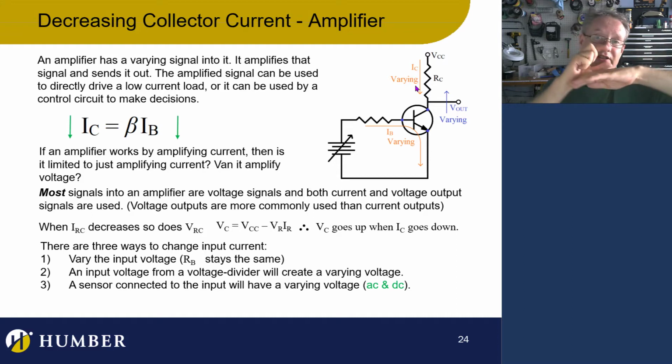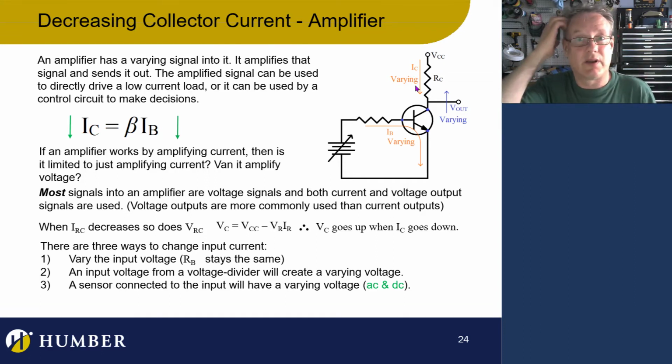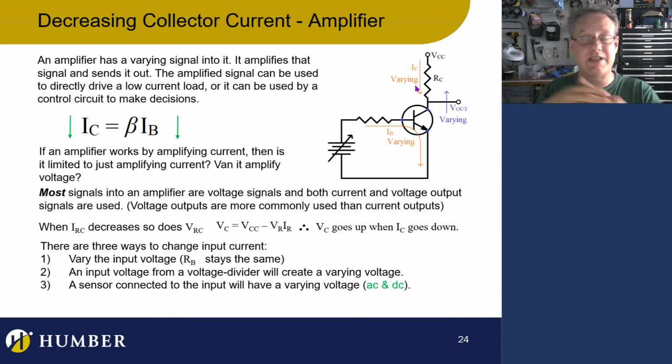What's going to happen is it's going to have a voltage drop across the BJT, just like a resistor or something. Actually, Kirchhoff's voltage law for a series circuit works here. So if this BJT was half open and half closed, and I had 10 volts here, my VCC, I would have 5 volts dropping across this and 5 volts dropping across this. So I'm going to have 5 volts out here. It'll be interesting. If I study the voltage potential right here, it's going to be 5 volts.